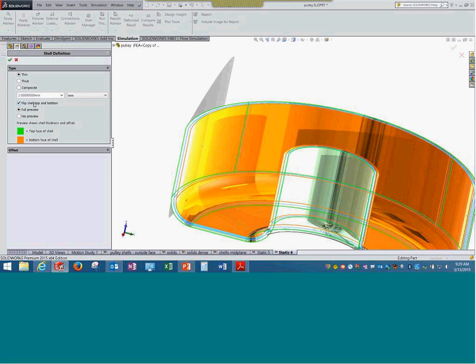But if there are multiple surfaces or multiple shell elements, definitely it will affect, and you might see addition of stresses incorrectly at the connections as well as throughout the geometry. So it may not affect displacement, but for stresses it will make a big difference.